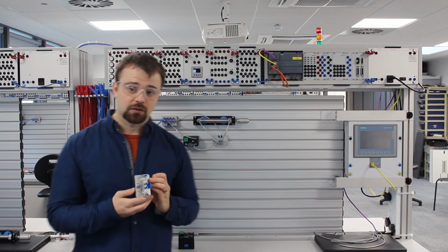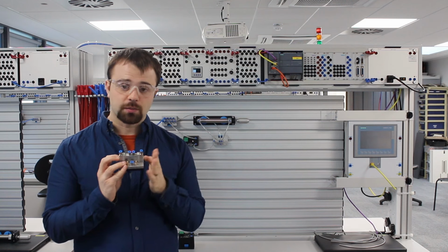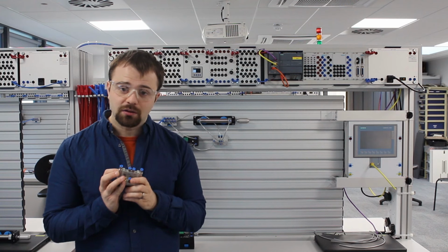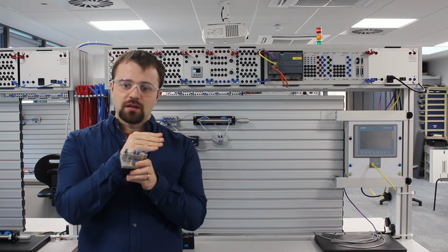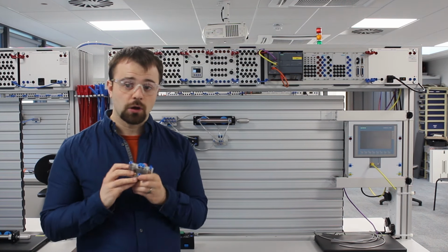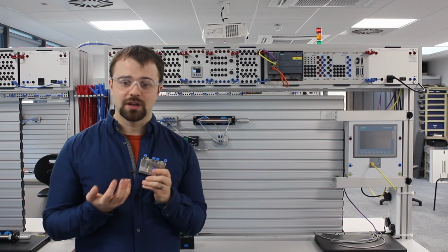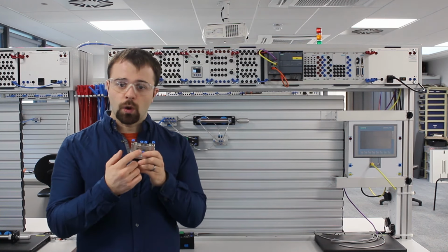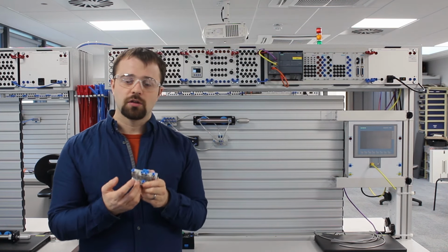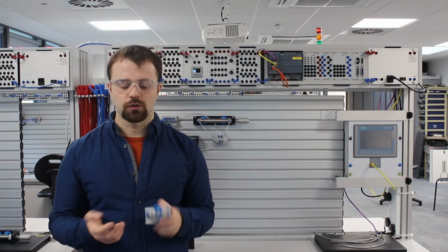Do you remember how in the previous example we had 1-4 that allowed us to connect 1 to 4? Well, this valve also has a pilot on the other side, 1-2, allowing us to connect 1 to 2. What that means is it will flop between the two states, but it will never spring back. This can pose a problem because it means we do not know currently what the state of this valve is. It will be in the state of whoever left it last. So, 1 could be connected to 2, but it could also be connected to 4. All we need to do though is plug it into our circuit to work out which way it was previously configured, and it should sort itself out.